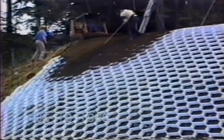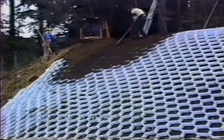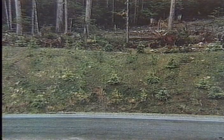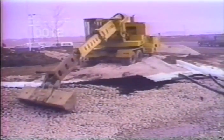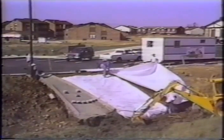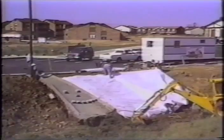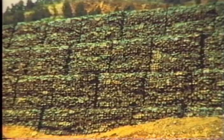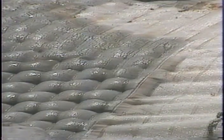Where some structural support is required, flexible webs or cells are filled with soil. The three-dimensional cells confine and reinforce the soil, allowing normal drainage but holding the infill in place. They can then be vegetated to give the native cover which controls the erosion. Geosynthetic cell structures can also be filled with crushed gravel, forming a reinforced mattress for improved bearing capacity. Geotextiles have long been used as filters beneath permanent hard armor systems of riprap, concrete interlocking blocks, gabions, or geosynthetic forms filled with grout.